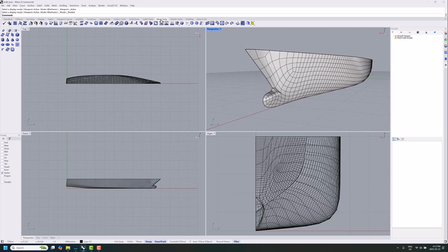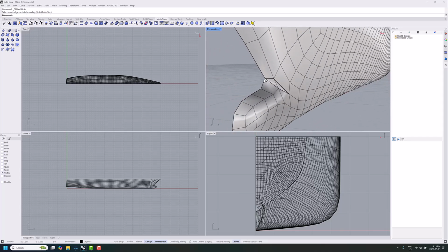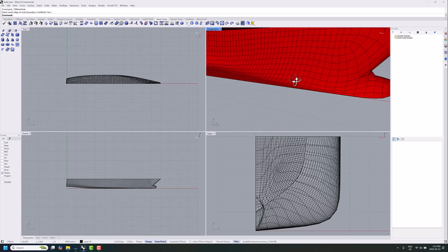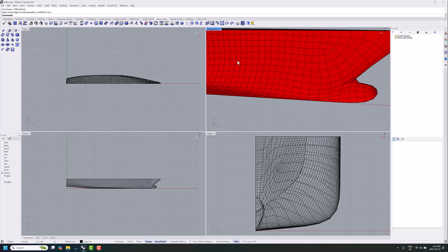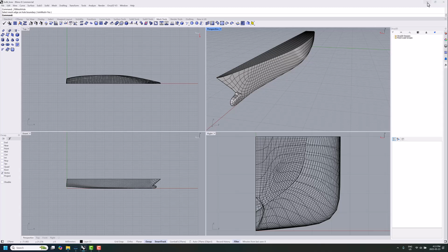This is actually really easy to fix quickly. If you're in Rhino and you go to the mesh tools, you can pick the Fill Mesh button, and then you pick an edge, and it pretty much fixes it right there for you. So we've got two extra little polygons there. What you can do is save this, export as an OBJ, and start the process again. I've actually done that with a second copy of the project I'm working with here.